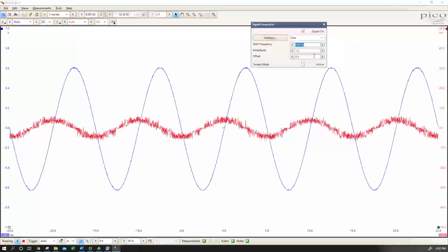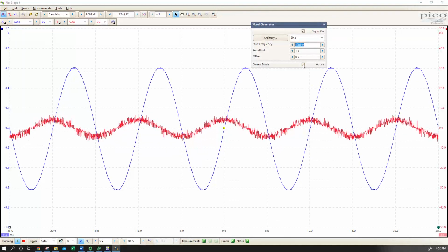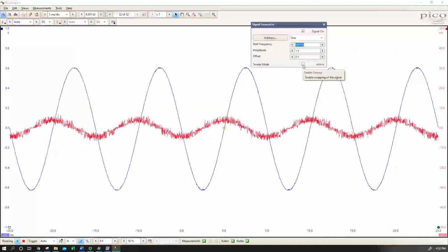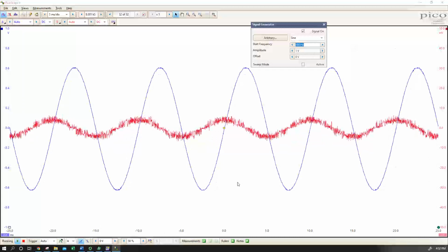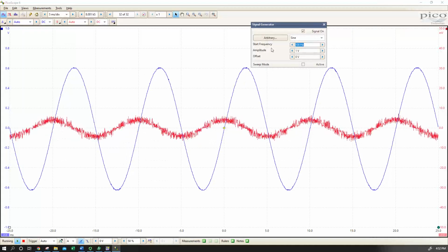Now earlier we showed what a frequency-based signal looked like. Now we're back to our regular scope, time-based signal. We can use a sweep mode with our scope. One of the problems with that is it's sometimes difficult for the scope to keep the trigger and the auto-scaling, both time-based and our voltage signal on the Y, over a large region. And so sometimes it just looks jumbled. I find in this case it's easier to just select some frequency.